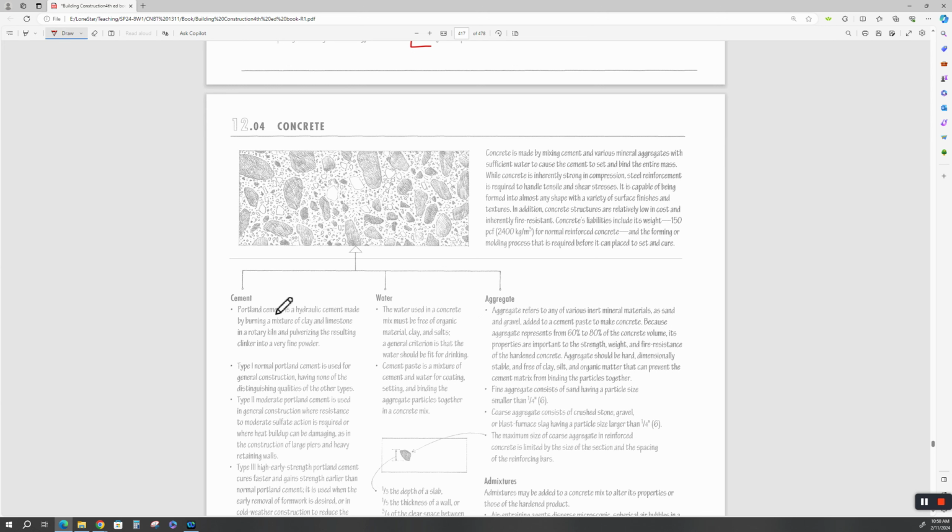The American Concrete Institute and the Portland Cement Association started doing research. I was on one of the committees, and it became quite prevalent to not use so much Portland cement and substitute some of that with fly ash. As an engineer, you would go through your mix calculations and figure out what percentage of fly ash we can use, how much Portland cement we're saving, and what our ultimate strength is. Is it going to affect it?